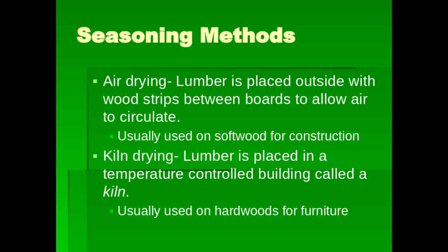Kiln drying. Lumber is placed in a temperature-controlled building called a kiln, usually used on hardwoods for furniture because we can get the moisture content down to a good level for making furniture.